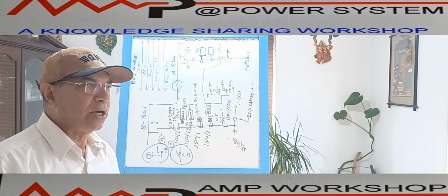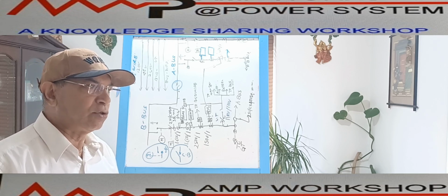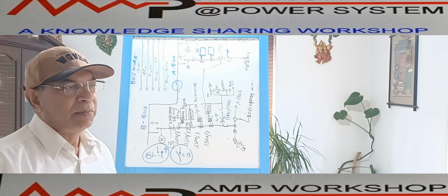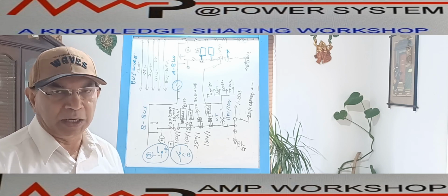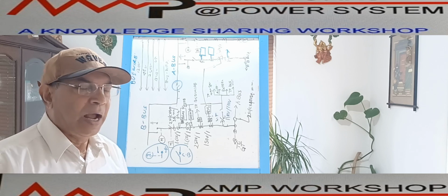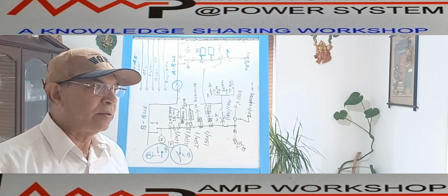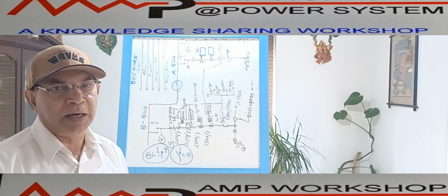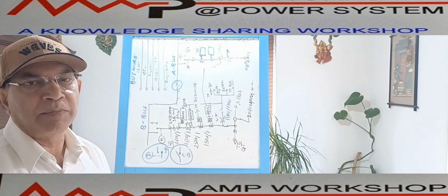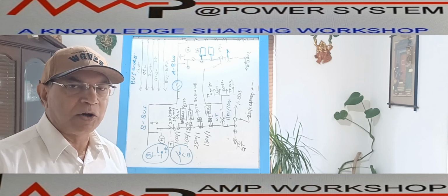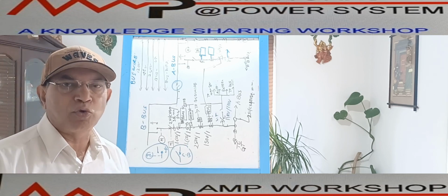That means this switchgear, as we have already discussed, has two bus bars, bus bar A and bus bar B. So these generators will be connected to both bus A and bus B by a dual feeder arrangement. All the transformers and motor feeders will be single connected, because they are single feeders, but big motors or the process compressor motors, and the transformers, will be connected like a generator feeder, dual feeders. Based on that, we are going to develop the single line diagram, with all the power equipment sizing in our hand. So I am showing one typical for the generators or dual feeder arrangement.